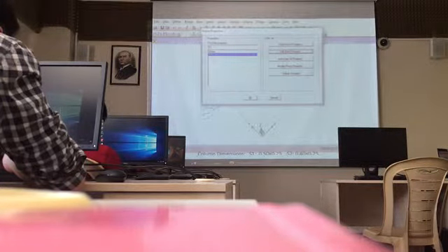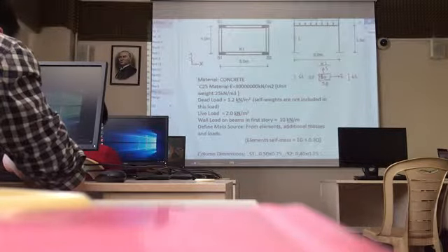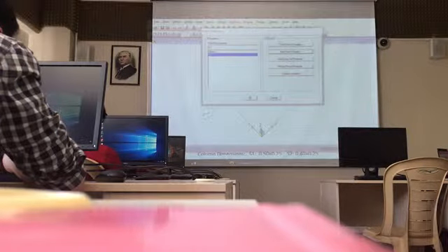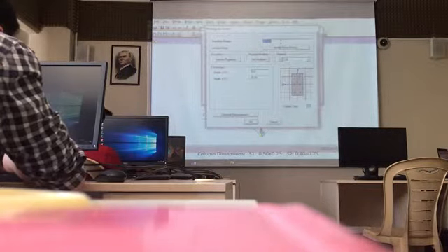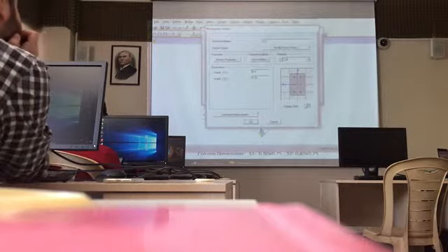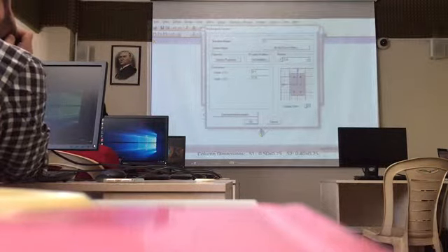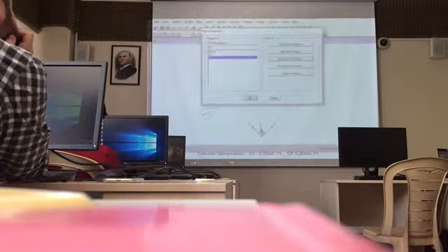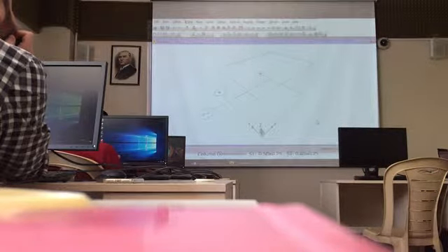And we have another one. What is that? S2 is similar to S1. Therefore, I'm going to select this one, add copy of property. Only the length will change. Its name is S2, and this will be 0.4. And concrete reinforcement is the same. Now we are all set.